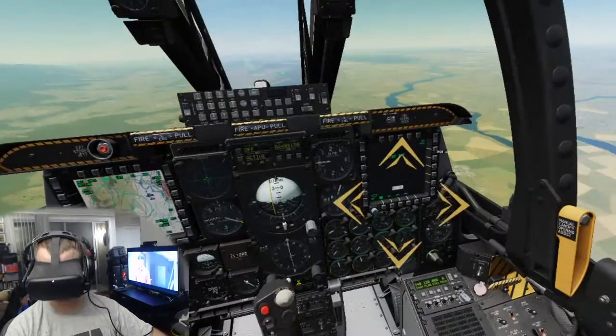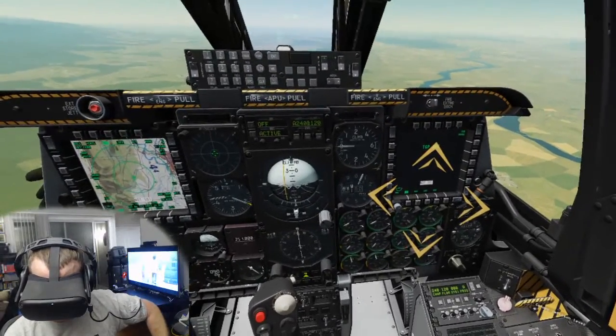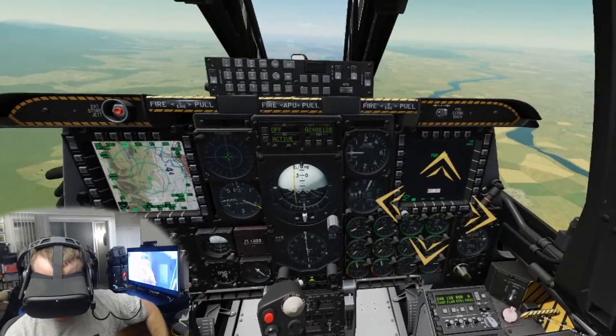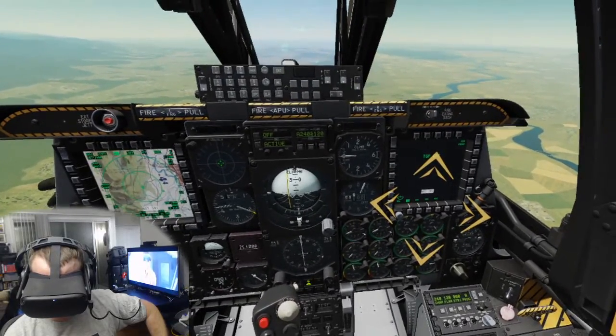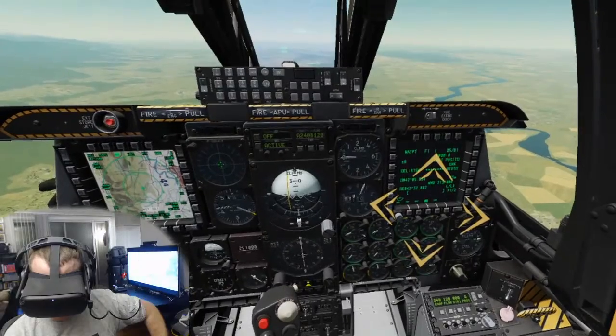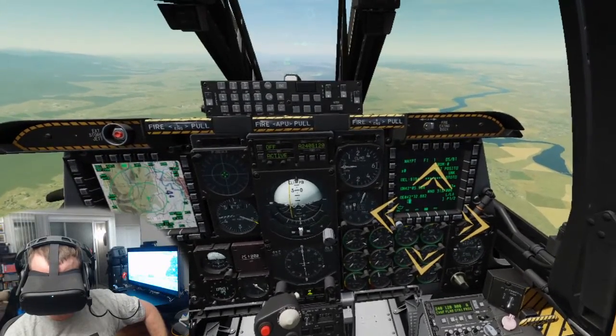Because we covered TACAN navigation previously, we'll use the GPS component of the IGI to navigate to our destination in this lesson. The CDU divert page lists the 4 closest air bases programmed in the CDU as selectable waypoints. To access this page, let's first open the CDU page on the right MFCD with OSB 13.